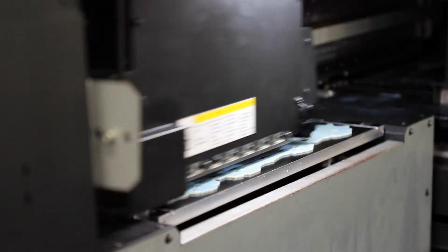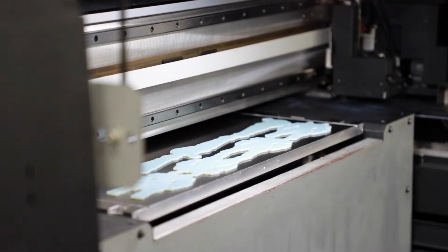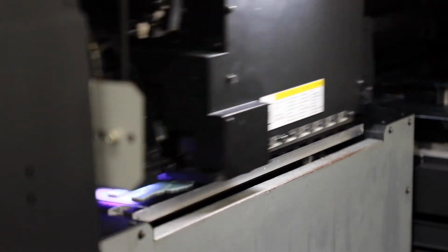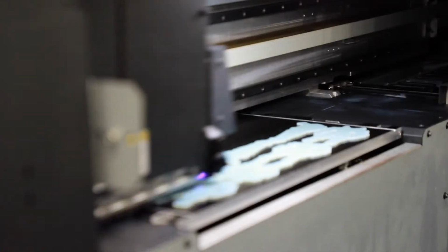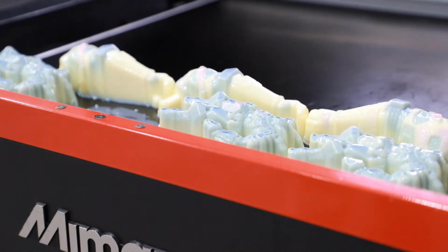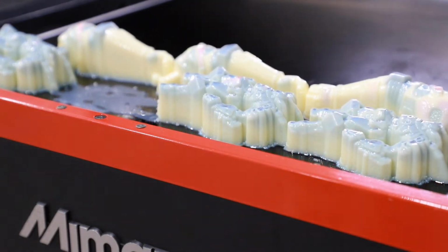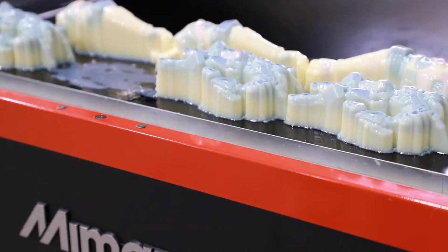So I'll open the cover up while it's printing so you can get a better view of what's going on. As the print carriage is going back and forth, you'll see the UV LED lamps illuminating on the left and right hand side. The flattening roller is in between the left-hand lamp and the print carriage. The table itself is moving in and out, and at the same time, it's moving in the Z-axis up and down. This is what gives us the different layer thicknesses. The movement of the bed is controlled by a series of ball screw drives. These are highly accurate and make sure that every droplet on the machine is placed exactly where it needs to go.